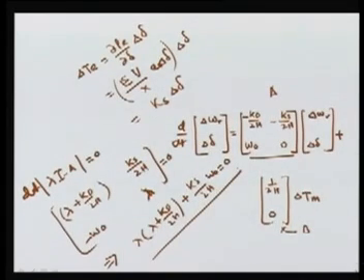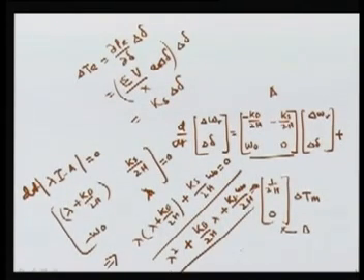This quadratic equation we can solve, and it will be lambda square plus kd upon twice h lambda plus ks omega naught over 2h equal to 0. Now if you solve, you will get the two values of lambda, lambda 1 and lambda 2, the two roots of this system.